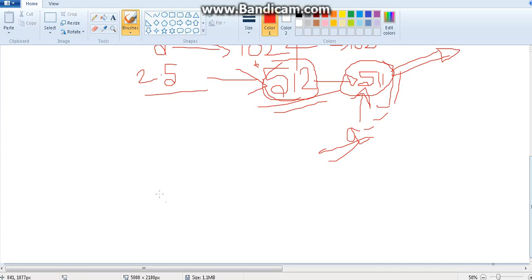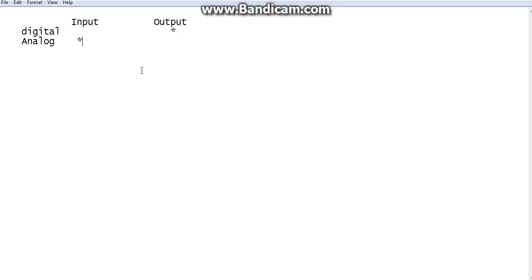So just do a small exercise before we get into code. What if you are giving 1.25 voltage? How many units will it be? From this picture you can realize, if you are giving a 1.25 voltage from a sensor to Arduino, what will the value be? Not the number of units but the value. So first you find the number of units and you just have to subtract 1 because it starts from 0, so you add the -1 and you will get the value.